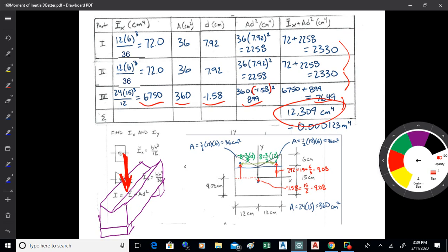Yes, exactly right, and it's a little confusing sometimes because for the x moment of inertia, you're using a y distance. For centroids, it's not that way. If you're measuring in the x direction, you call it x bar. So they're a little different in how they're notated. Just be aware that the centroid notation refers to the direction you measure.